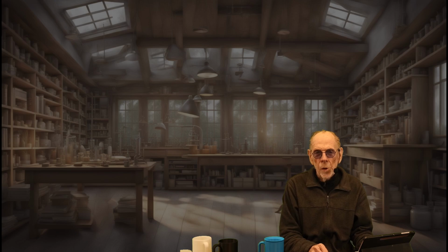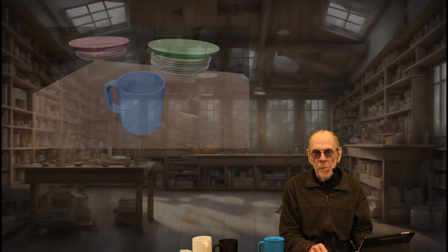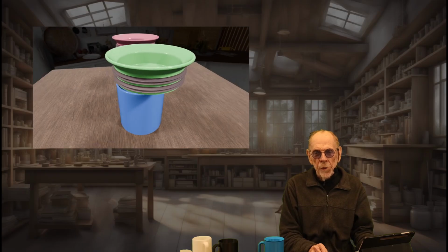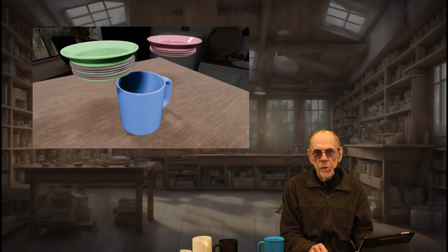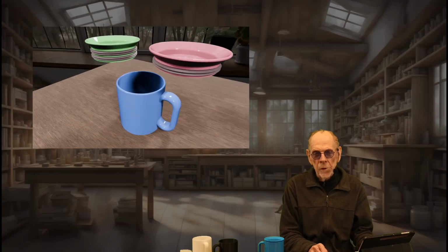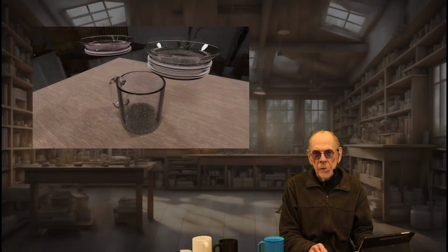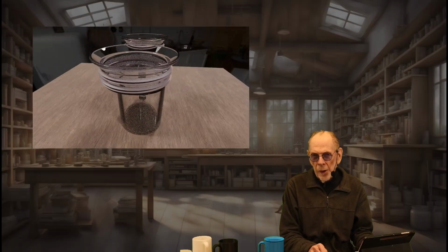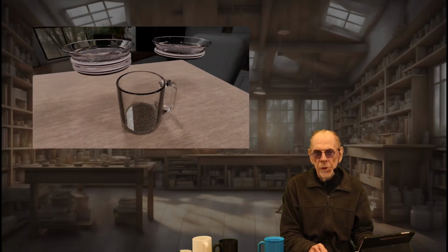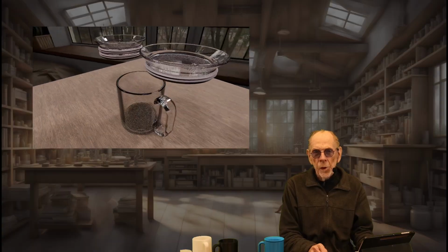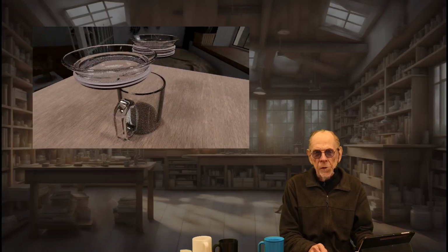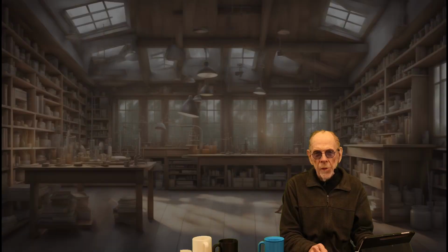Now we start the main drawing, the cup body. This is a more complex design than in my past tutorials, because as time passes I've learned more efficient ways to use SolveSpace and exploit its more advanced features. One goal of this project is to explain how to create a reference diagram that controls the dimensions for the entire project. The other drawings rely on this reference to set sizes, which means you can change values in this reference diagram and the entire project is resized.